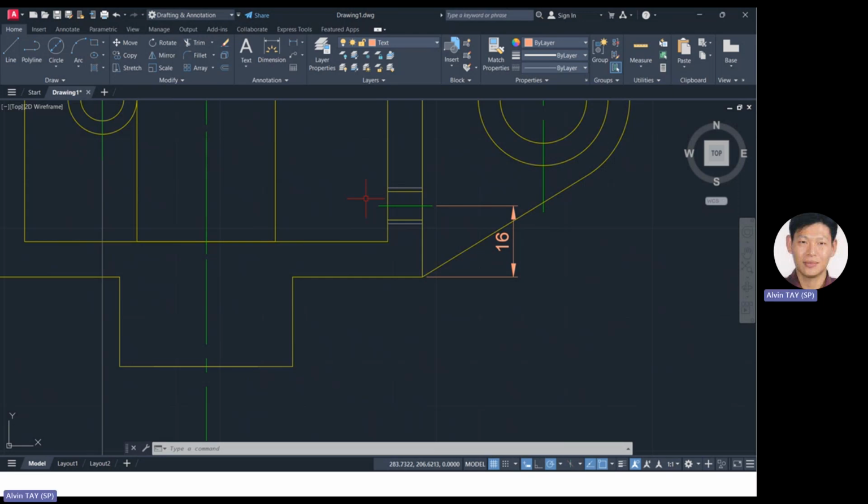Then the next thing we need to do is what? After converting, what do you do? You will do the wavy lines. Spline, remember? Spline. Okay, how to do wavy lines? Spline. So how to do spline? Okay, the trick is like this. My recommendation for you guys is you draw the spline from the outside. You draw it there. Don't draw at the point here. No. Okay, so this is not correct. If I move at the three markers, even there, harder.